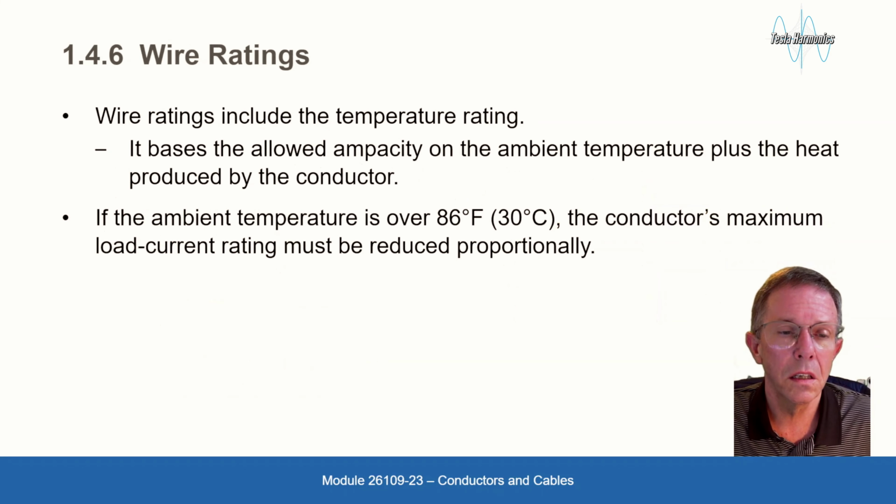Wire ratings. Wire ratings include the temperature rating. It's based on the allowed ampacity, the ambient temperature plus the heat produced by the conductor. If the ambient temperature is over 86 degrees Fahrenheit or 30 degrees Celsius, the conductor's maximum load current carrying rating must be reduced proportionally.